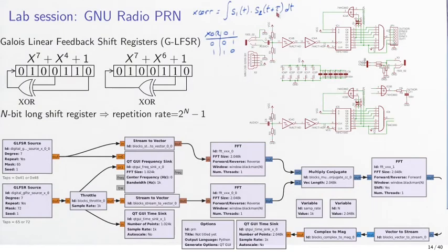How do we create the tau offset? Well, actually, we're going to feed these two LFSR sequences with the audio output of a computer used as a signal generator, and the two signals of a stereo output. So it's a coherent sound card because both outputs are clocked from the same local oscillator, and we create a slight offset in the frequency feeding these two feedback shift registers. How do we do this? Of course, using GNU Radio.